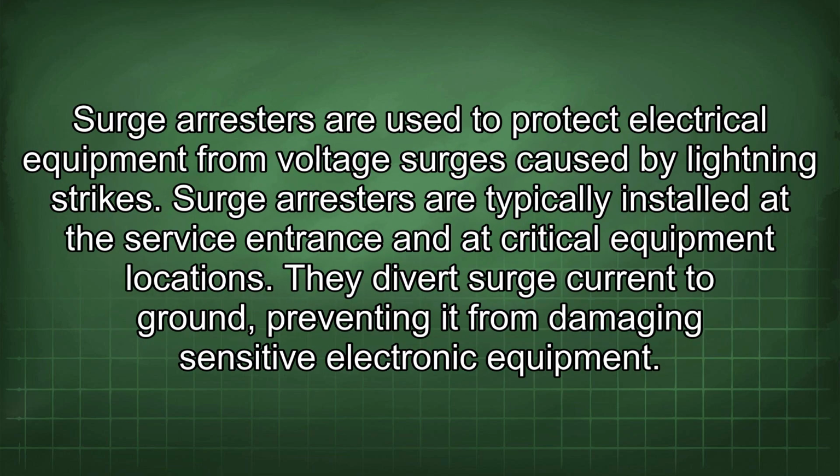Surge arresters are used to protect electrical equipment from voltage surges caused by lightning strikes. Surge arresters are typically installed at the service entrance and the critical equipment locations. They divert surge current to ground, preventing it from damaging sensitive electronic equipment.